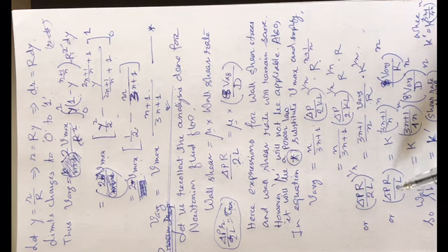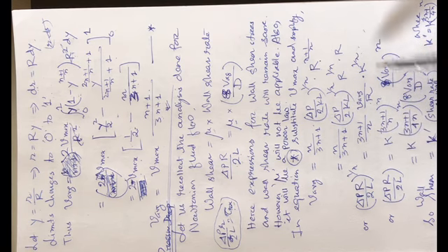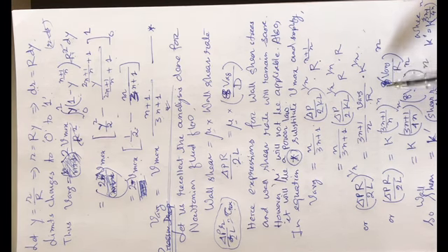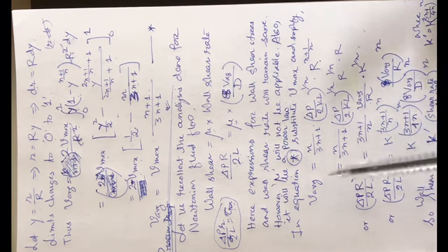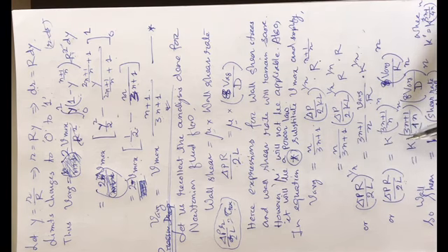So then delta P by R divided by 2L is equal to, actually we took the nth power for both these sides, then we get this expression: 3n plus 1 by n to the power n, and V average by R to the power n. Okay, so then what is it? It is the wall shear expression, which is equal to k multiplied by, we are doing some modification. It is not 8 times as of now. So we are doing modification here.